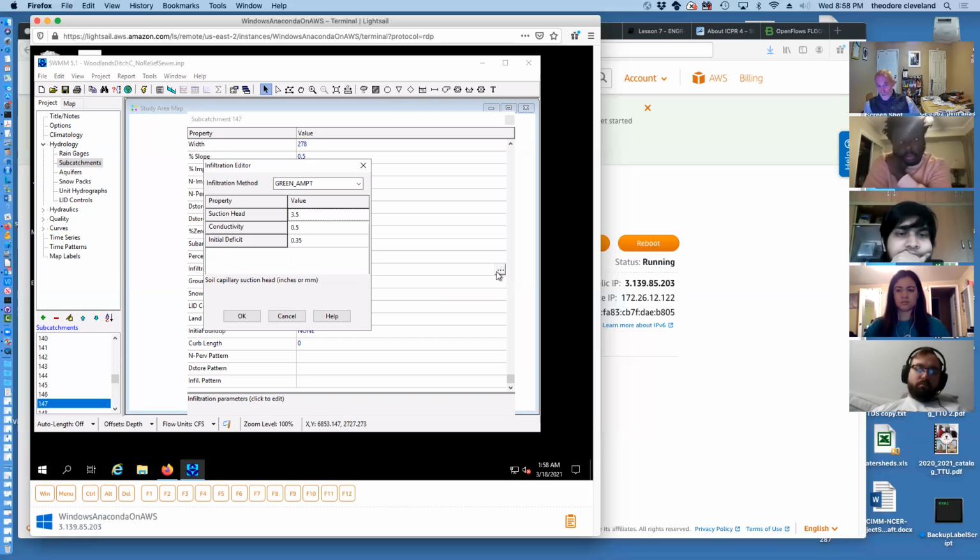Soil physics is an incredibly complicated topic. The governing one-dimensional model in common use is called Richards' equation, and the Green-Ampt is a simplified solution to the Richards' equation. So it's treating the surface that contacts the bottom of this storage element as a sponge with very well-known physical properties, and they're listed here.